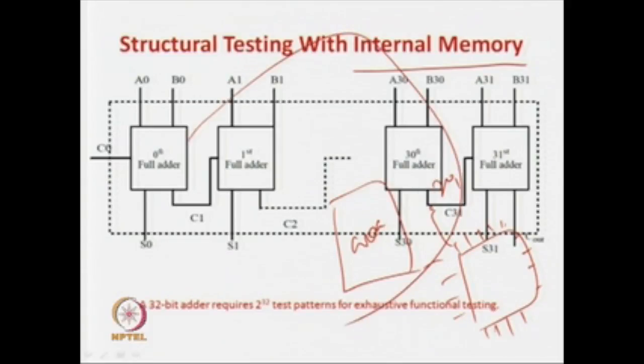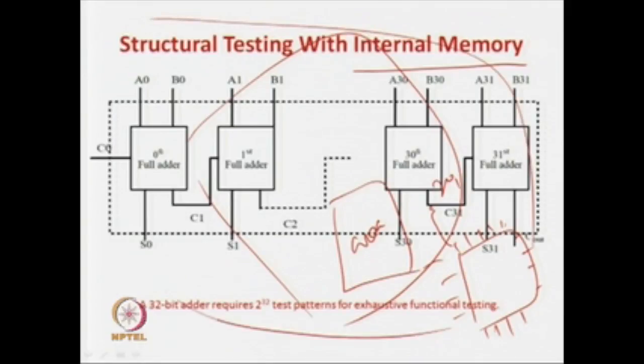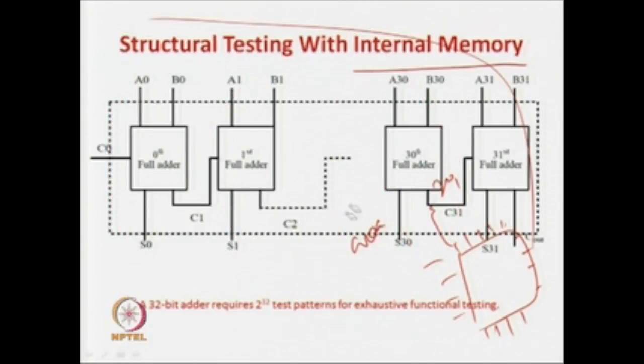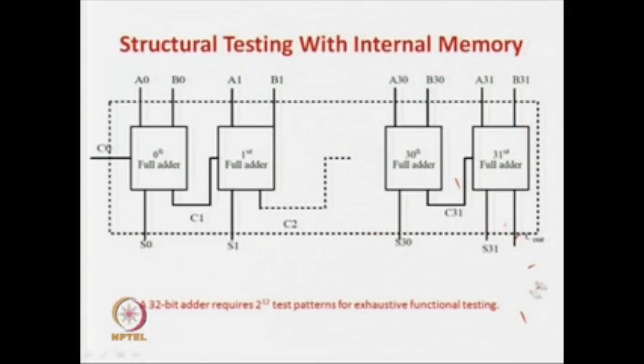A chip with 20,000 pins may be as large as your laptop. So, this one chip may be as large as your laptop if you require 20,000 input pins. That is not a good idea, and I cannot manufacture a chip whose size is about a laptop, but I can have a chip and give you another big area in the chip itself where you can have 20,000 muxes.